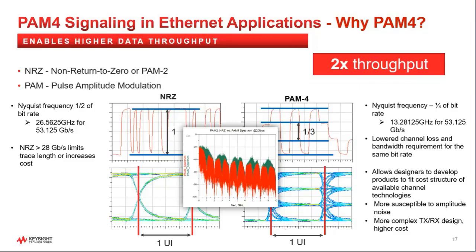The question is, why PAM4? PAM4 has its own advantages as well as disadvantages. One of the main benefits of PAM4 is having 2x throughput using the same channel. In other words, PAM4 allows design engineers to develop products to fit the cost structure of available channel technologies.